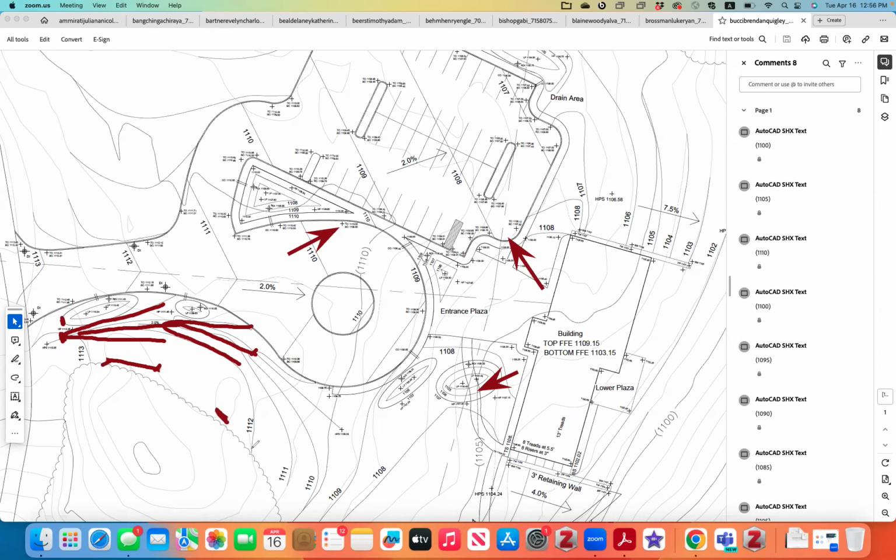Like that, I could make this more spacious, make my retention more spacious instead of this area. I can cut this down. I can move the 1102 even closer to the tree to make more room for my retention there. Okay. Once you graded this area, you need a side slope here as well.